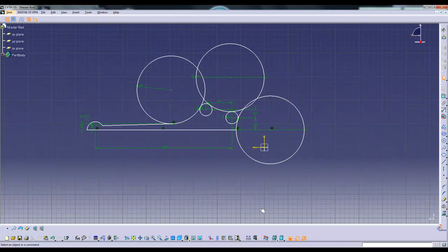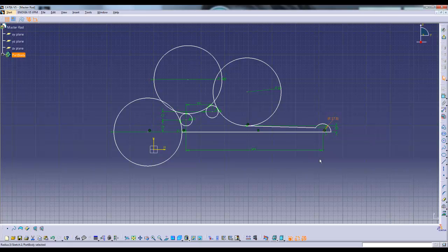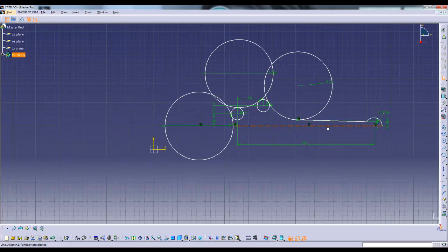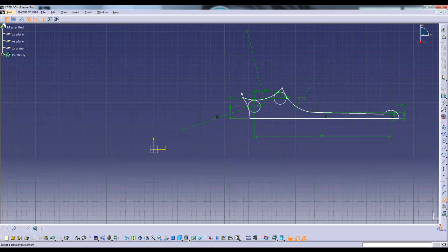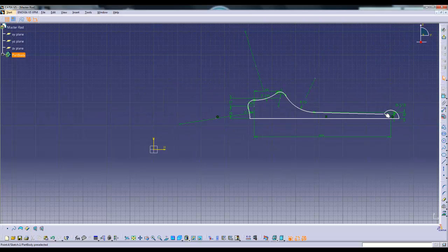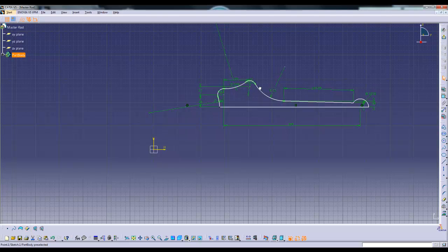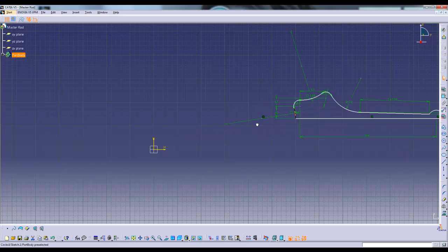Now, set the distance between the outer radius 13 circle and this point of origin of the arc at 289 millimeters. By moving around, we can see it's properly constrained. However, you can see right here, it is not fully constrained, so there must be one more constraint. Making that a length will ensure that that 17.5 radius arc stays constant.